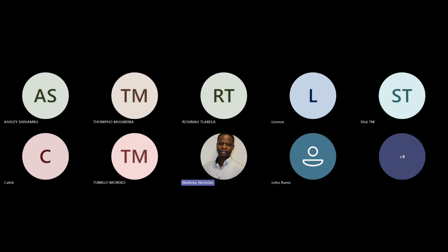whereby we were just using a push button to actuate our cylinder, right? Our cylinder was having a spring, so that the cylinder retracts automatically once you remove your hand, or your finger, from the push button, right? So that is how the pneumatic circuit looks like, and that is how your electrical circuit looks like.